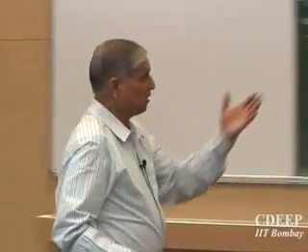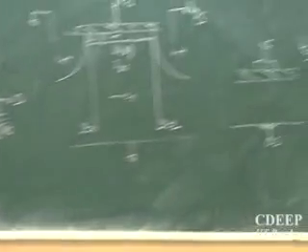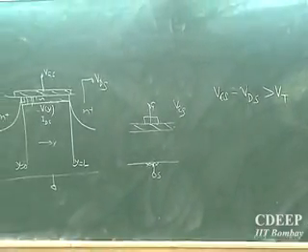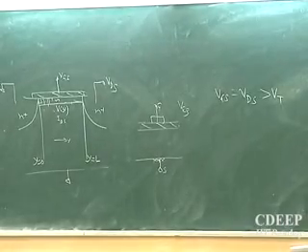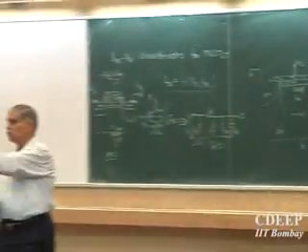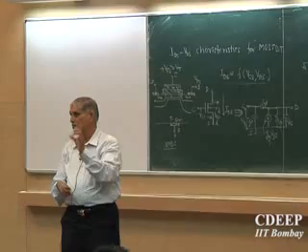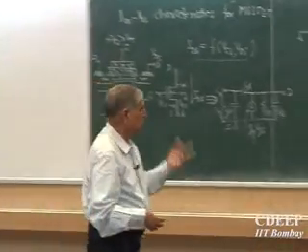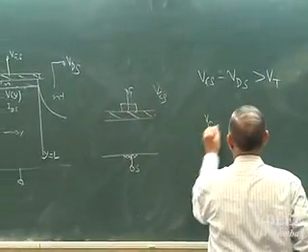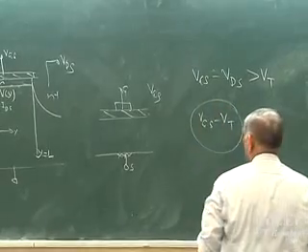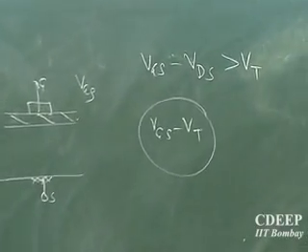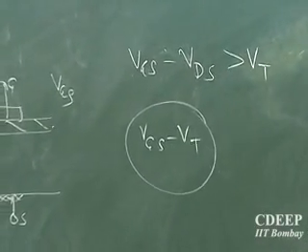Now this is the difference between a capacitor and a MOS transistor. Is that clear? Because in a MOS transistor, IDS gives you a voltage drop at the substrate side. Even if the substrate is grounded, the upper layer is now connected from 0 to VDS, so the channel has this voltage drop. Now this is something interesting. The larger the difference, the larger is VGS minus VT, and the larger is the number of inversion carriers it can create. So where do you expect the maximum number of electrons?